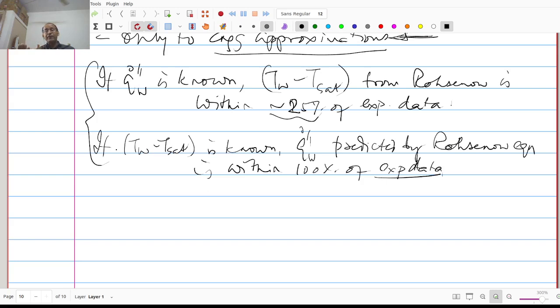If we enter the film boiling regime, the temperature difference between the wall and the steam matters. Power plants operate at about 150, 200, 250. Nowadays we have even supercritical boilers. But let us talk about boilers in which boiling is happening. So if the pressure of operation is like 200 atmospheres, at which the boiling point is close to 300 degrees Celsius, then the 1000 degree superheat would actually mean 1300 degrees Celsius on the wall.